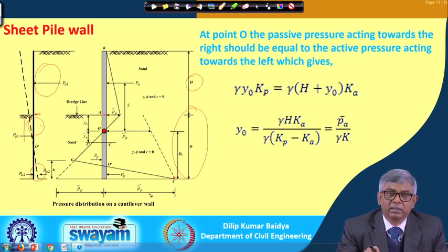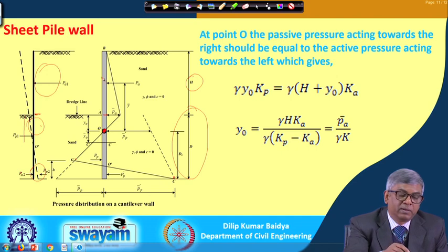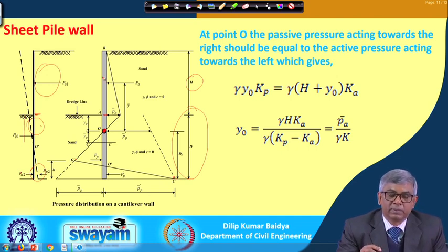That is one thing you have to find out, the depth of embedment. At the same time, depending upon your bending moment you have to choose the section of the sheet pile wall, so you also have to find out the bending moment. That part I may not discuss at length; mostly I will try to find out the depth of embedment, and that is the only part I will discuss at length.